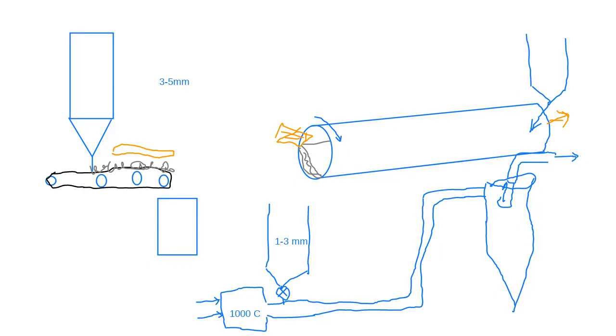Okay. So there are dry particles coming out the bottom, and there's wet hot air coming out the top. Okay, Philip. So would we then try to minimize the horizontal piping sections in such a dryer? Yes, you would. And again, you try and actually avoid elbows. It's not going to be an elbow. It will be a 90-degree curved pipe.